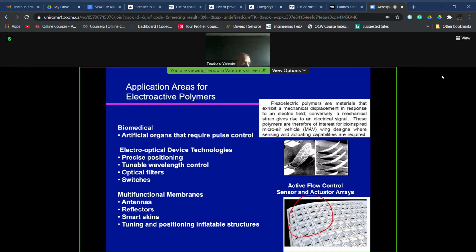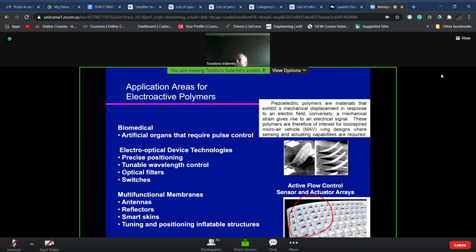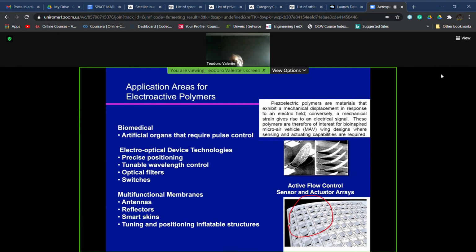Again, you need to instrument the part in which the piezo polymer is inserted, but this is not very complicated, in order to measure the voltage, and so have the result of the applied stress, which makes the deformation, that is the strain, exist on the piezo materials, which is responsible for the voltage that is generated.